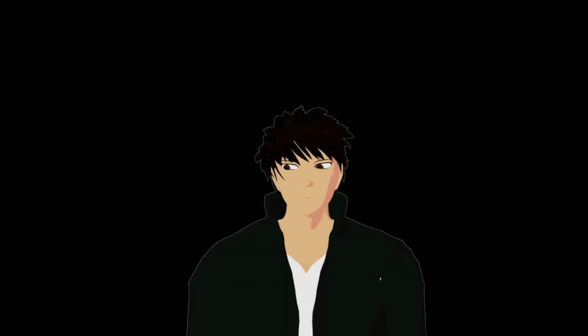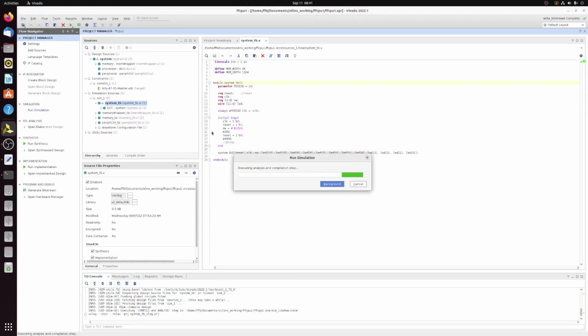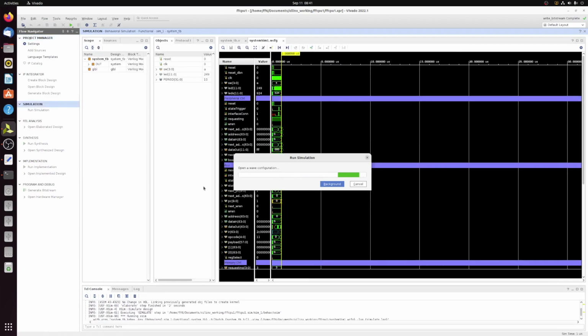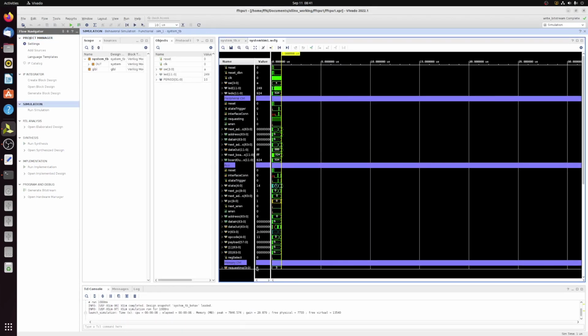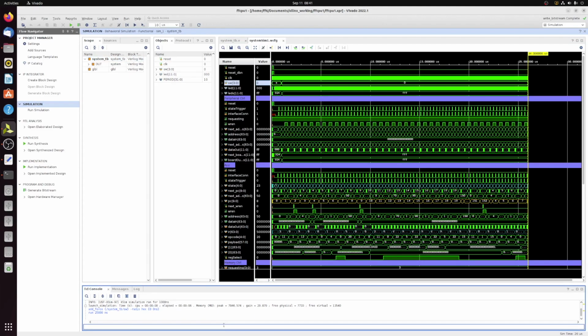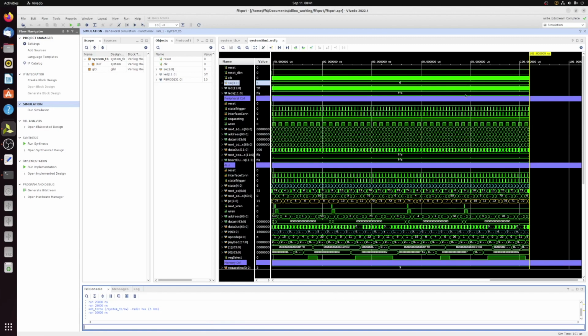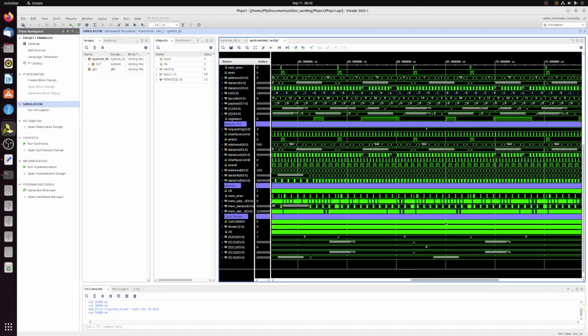You'll also notice that the red LED isn't working. And this is a good chance to show you my debug process. So first, I run the simulation and try to recreate the problem. Since this is a functionality error, I can get away with using the behavioral simulation. You can force signal values to recreate the issue. Here, even though the red switch is high, the output LED value is staying low. So we go and we start tracking the signal through the system.